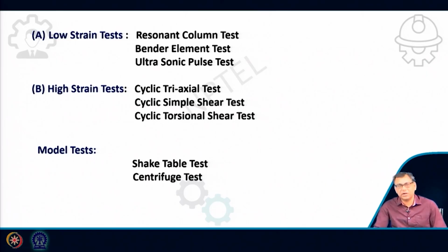What is model test? In the other laboratory tests we basically get the properties of the soil. In the model test we get the real behavior or response of a structure itself in the lab. I will discuss this model test, the shake table test and the centrifuge test.